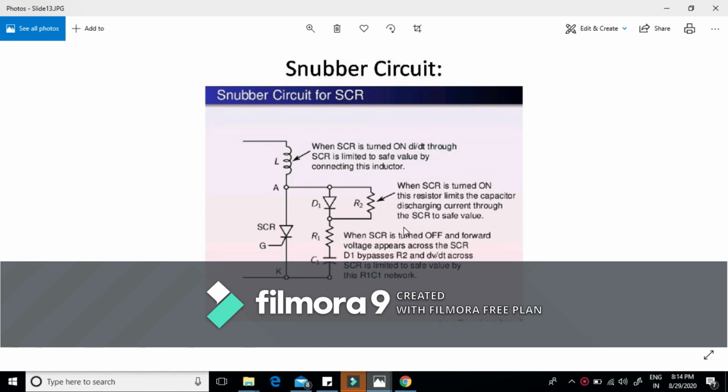At high frequency, these switching losses become more significant, and therefore energy recovery snubber circuits are used to either pump back the energy into the supply, that is into the power source, or to the load. Both active and passive snubber circuits are used for this purpose. In active snubber circuits, additional semiconductor switching devices are used.